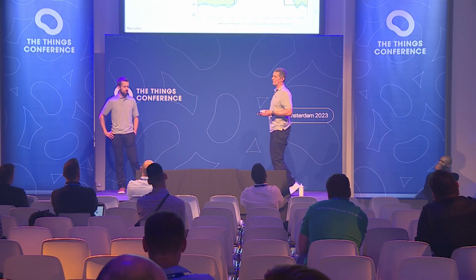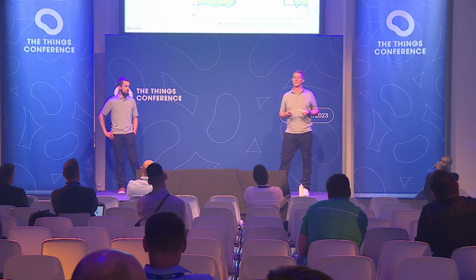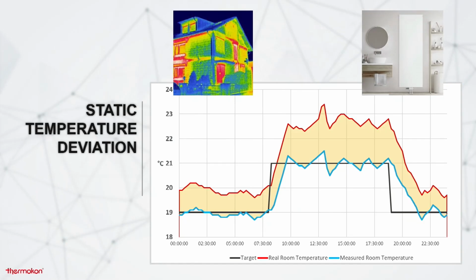The red line indicates a sensor value from an external temperature sensor installed inside the room on the wall. And you can clearly see that the temperature inside the room is always 1+ degree above the temperature measured on the window frame. This is a result of an improper place of installation for the temperature value.